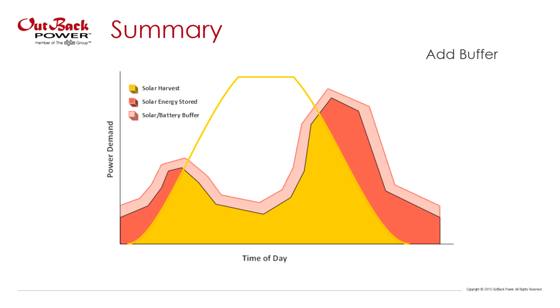You can add additional PV, so slightly oversize your array in relationship with your battery, and that's just to more quickly charge your batteries. Once your batteries are charged, though, you might not be using that power anymore because your batteries are full. So that's a possibility. You might not be fully using your array at all times, but you could be charging your batteries much faster.